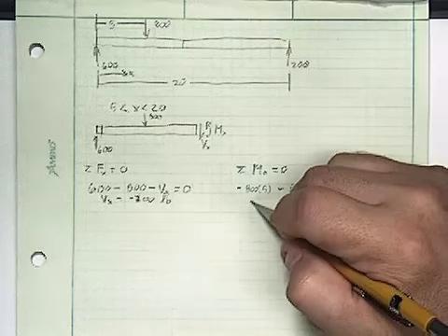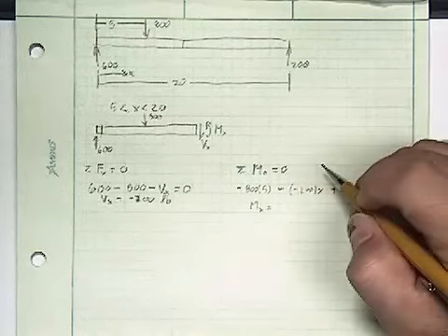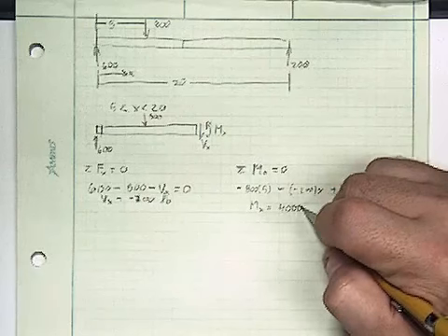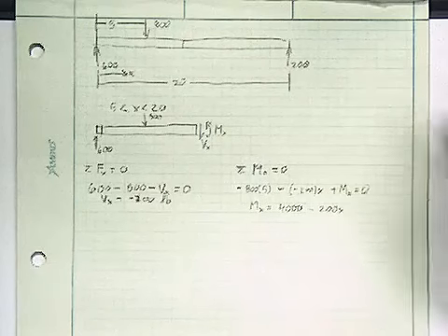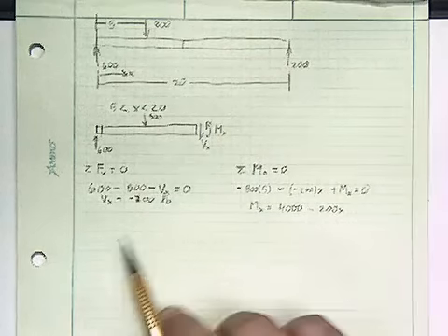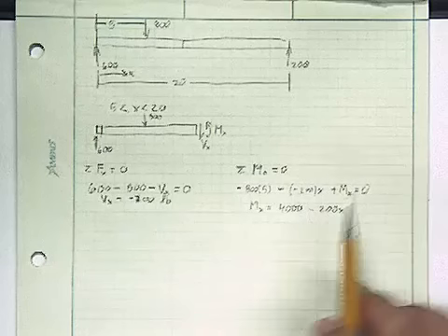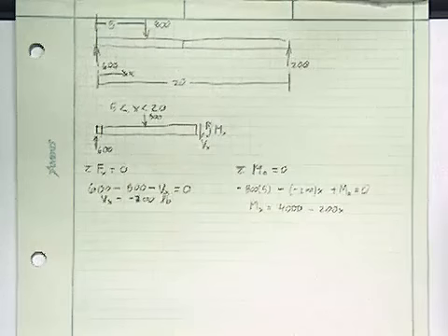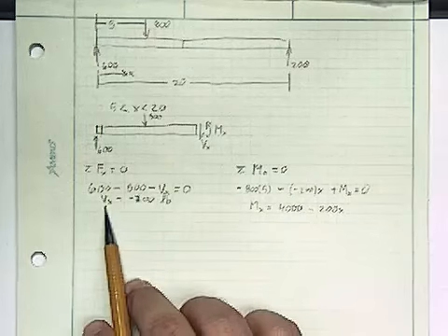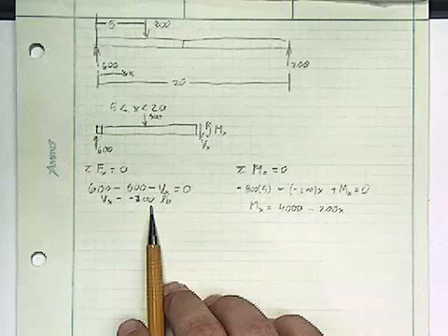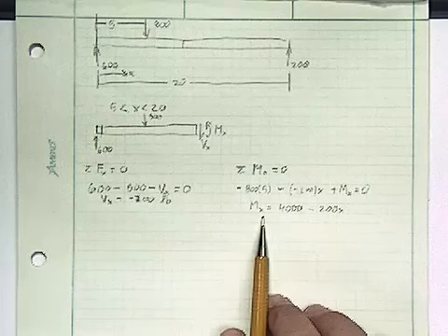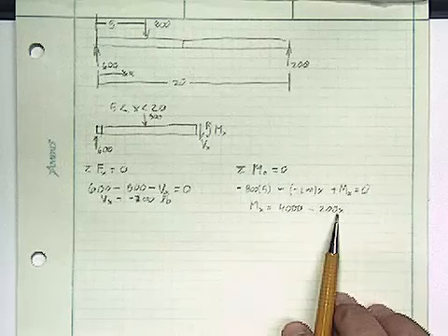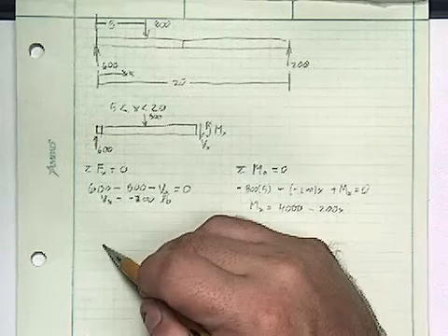So this is going to say that M(x) is equal to 4,000 minus 200x. So this is what's happening now anywhere from 5 to 20 inches. Notice V(x) is a constant. M is a function of x. So now let's do a graph.